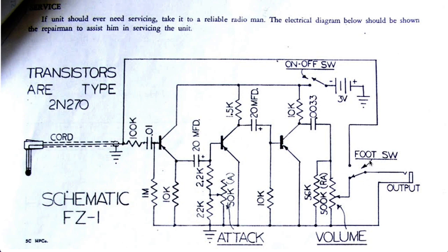There's some bypass switching here that lets you either bypass the effect or use the effect. And the guitar signal is coming in from the left. There's this 100K input resistor here. And if you look at the way the thing is biased, it is a little strange because we're used to seeing another resistor here at the base, but we don't. You can still analyze this using the techniques that we've derived. Anyway, notice that each stage is capacitively coupled, and that means we can consider the bias for each stage separately.